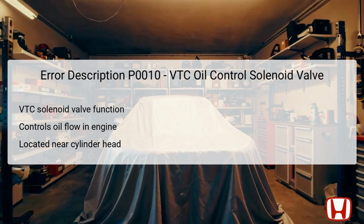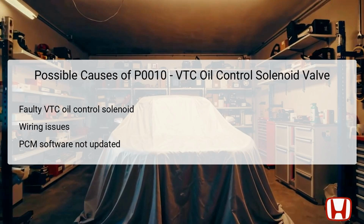By optimizing valve timing, it helps in improving acceleration, decreasing emissions, and maintaining engine longevity. When the ECU detects issues related to this valve, it triggers DTC P0010, indicating that further investigation is necessary to identify the underlying problem. Several factors can trigger DTC P0010.